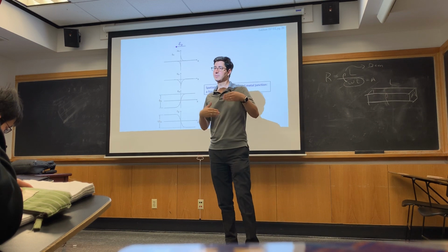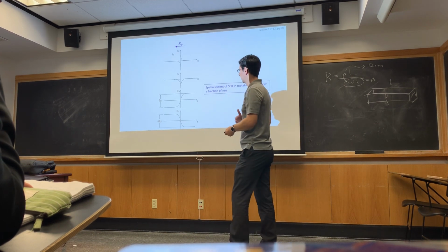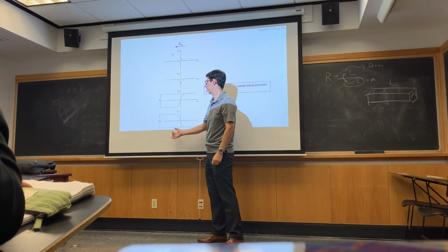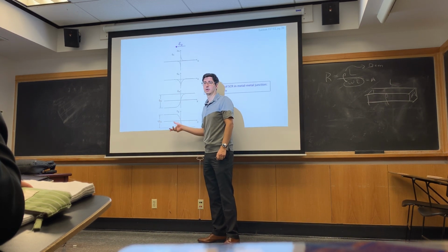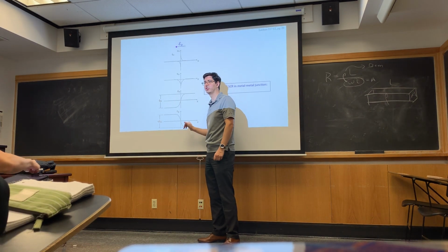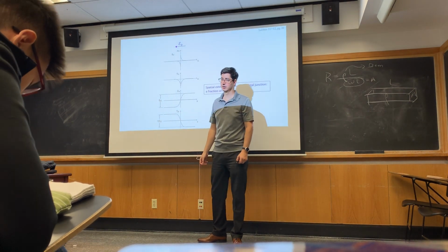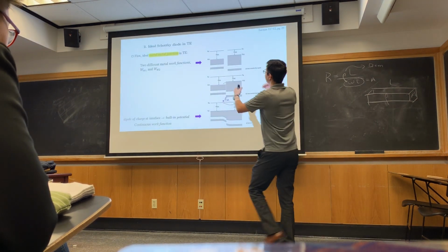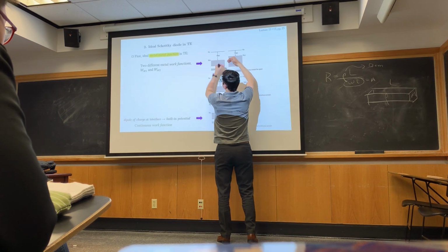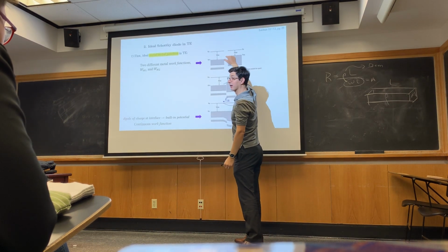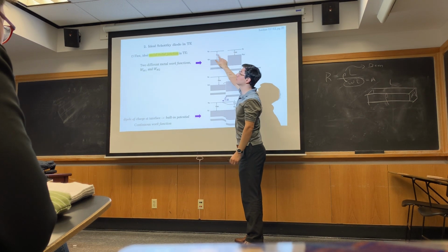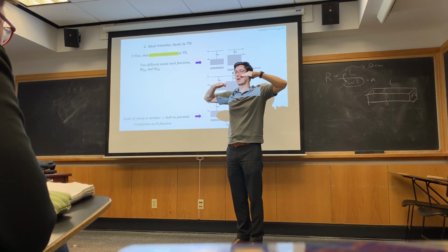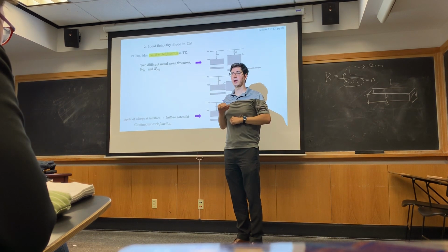Well, what we know is that the total potential difference across the structure has to equal phi bi. Or the total change in the potential energy has to be Q phi bi. Why? Because that's how much these bands had to move by to be aligned. Phi bi is just the difference in these work functions. So for me to reach equilibrium, I have to have something that gives me the band bending equal to phi bi.